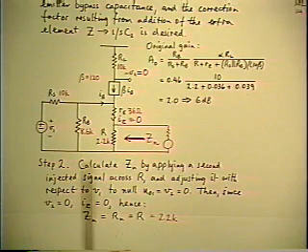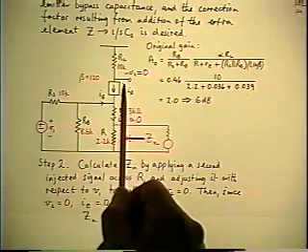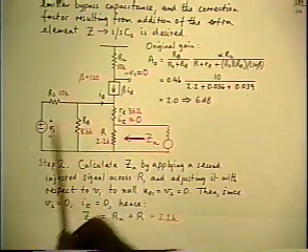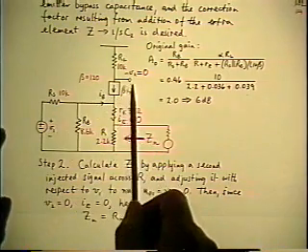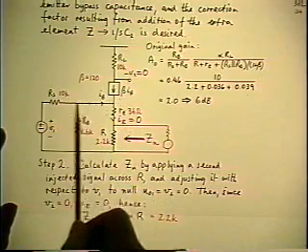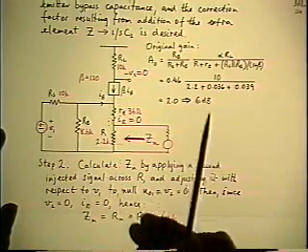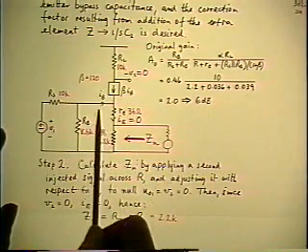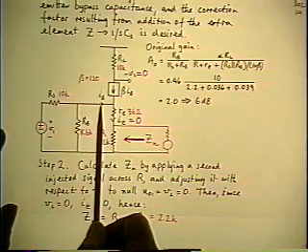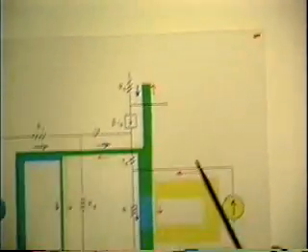So, in fact, all that you've used to calculate Zn is the fact that the null exists, and you don't need to know the V1 that caused it. That's why the argument simply followed the null back to the second source, and you never had to know what went out here. Now, if you want to know what goes on out there, you can find out. For example, the IB is zero as well. And that's what gives rise to the other interpretation in terms of the pictorial representation.